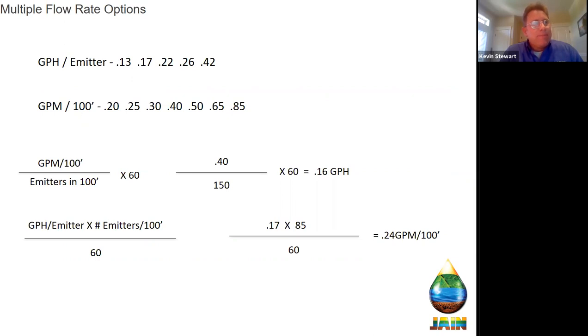So if you know what your Q100 is, there's a calculation where you can put that in and understand how many gallons per minute per acre you're dealing with, and that'll help you go back and make sure that you've got enough sizing in your pipe to handle that flow. In a lot of cases, you're looking at something like 20 gallons a minute per acre in, say, a 10-acre zone. And so it's just a matter of going back through the design process. Other than that, I don't know exactly why.